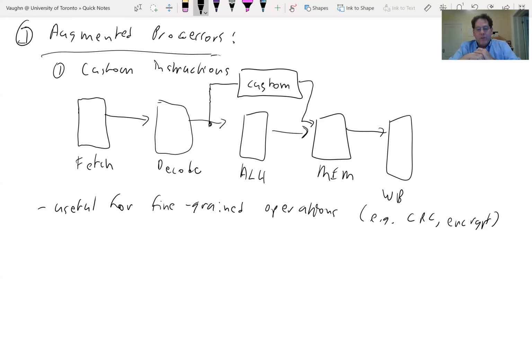You can do it on a regular processor, but you usually wind up having a whole bunch of XORs and shifts and OR operations to construct what you want. And you can build hardware that very efficiently does shifts. Shifts are just basically you wire things up differently if it's a fixed shift. And XOR, you program the truth tables in the lookup tables. You can make very efficient hardware for cyclic redundancy checks that does the shifts and these XORs.